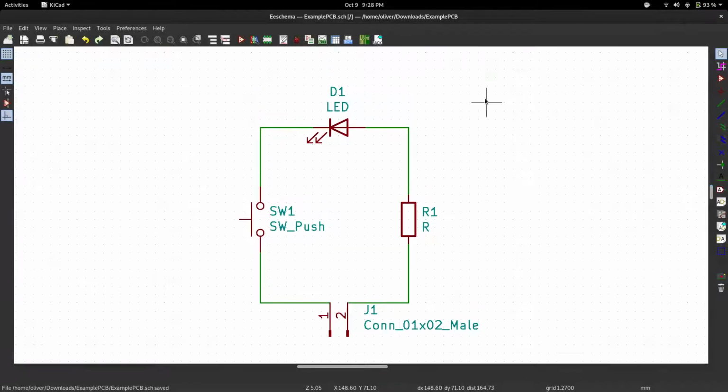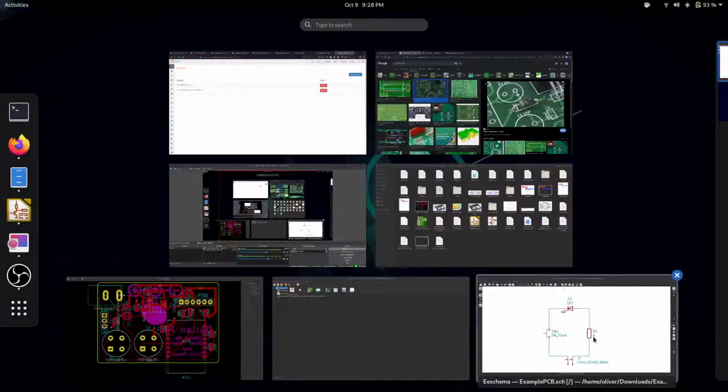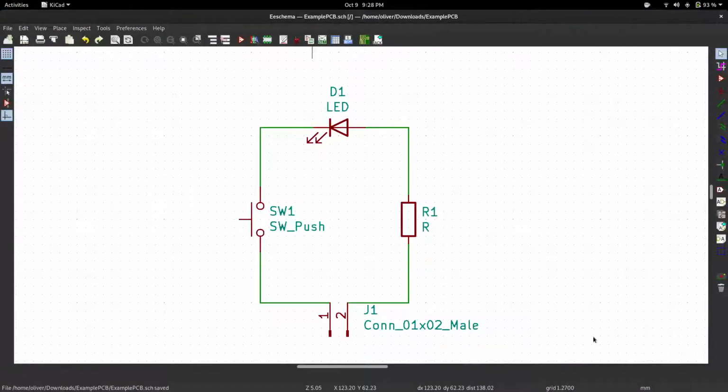So, next thing we got to do is assign PCB footprints. So this is the part we have to talk a bit more about. No questions yet. These schematic symbols don't have actual shapes. Like an LED on a PCB is probably going to be 2 holes in the PCB, with copper, so basically two vias next to each other.